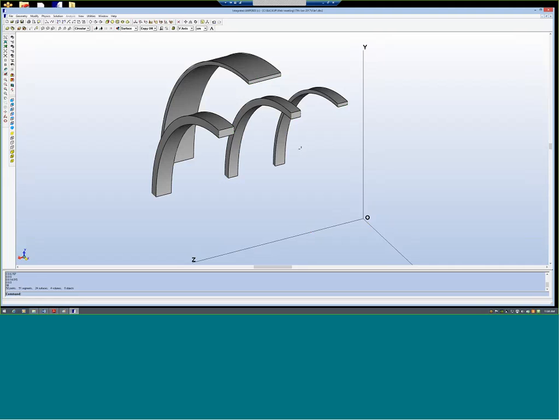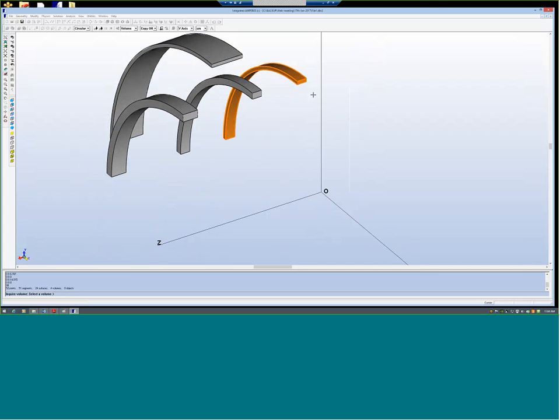So this is a part of the coils. See here in the AMPERES program, it is important that any volume that carries current should have just 6 surfaces. For example, you observe this piece of coil, this volume, it has got 6 surfaces. This is surface number 1, 2, 3, 4.